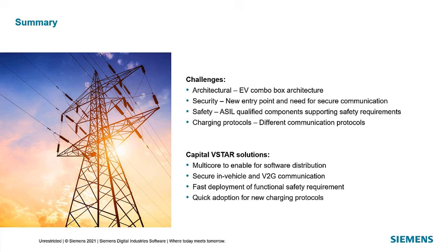Safety challenges: ASIL qualified components to support safety requirements. Charging protocol: different charging protocol standards require distinct communication. IEC 61851 requires CAN, whereas ISO 15118 requires TCP/IP.